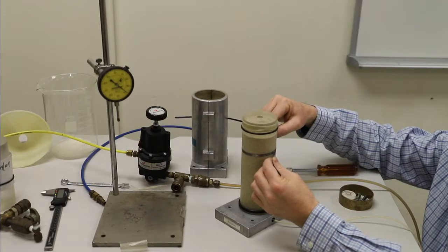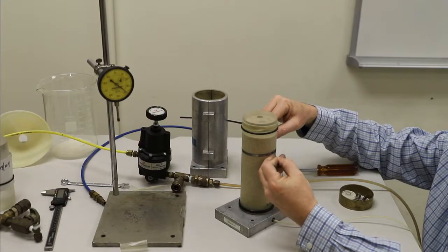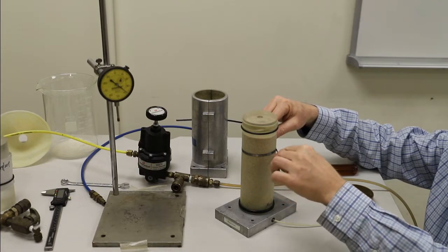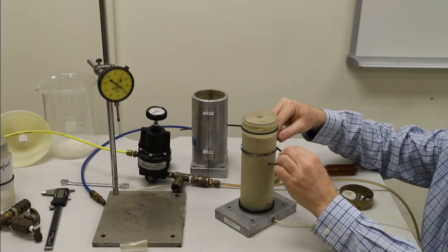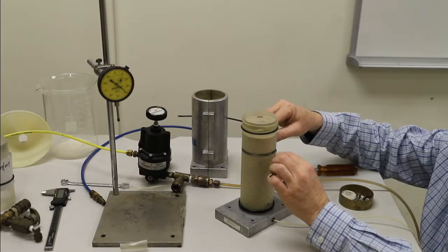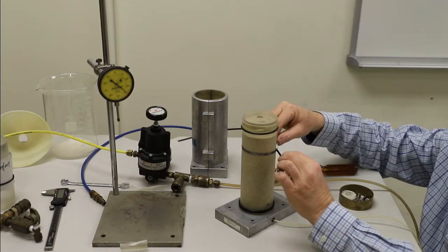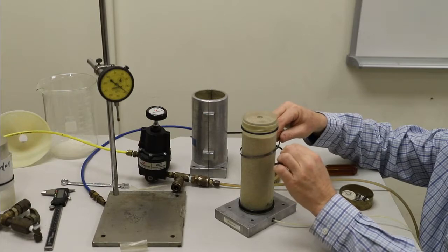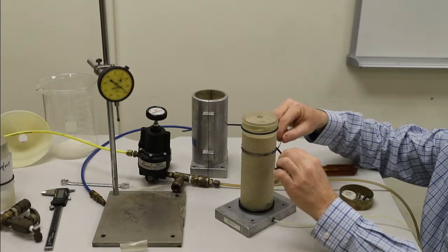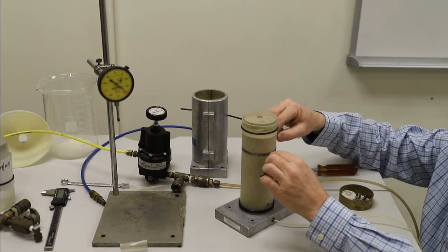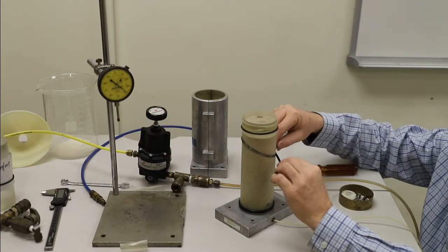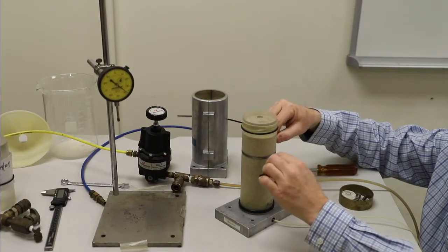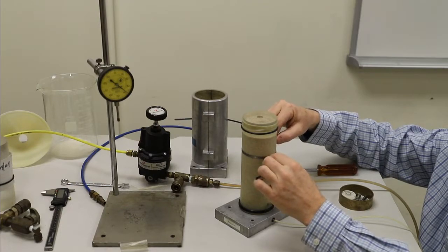Now, these are interesting devices in that there's always some measurement error with almost any measurement you take, but it's not always random. So you don't want to take multiple measurements in the same place and then take the average, because there's a very one-sided bias here. If you get this caliper or this pi tape not level, then you're not really around the circumference, right? You're not wrapped around the circumference. You are measuring some sort of an oval, right, at an angle. So if you take a few measurements in a row, you always take the smallest value at a given elevation.